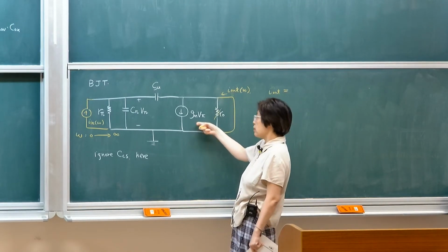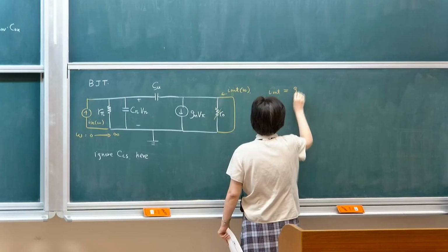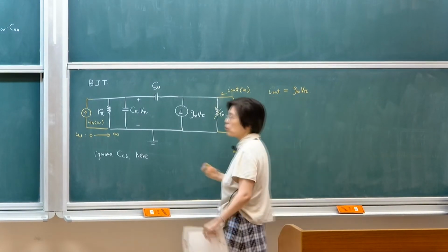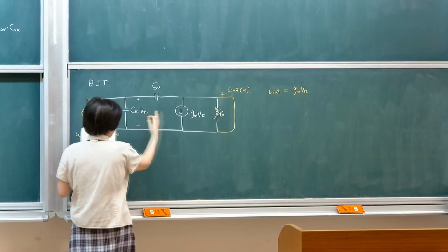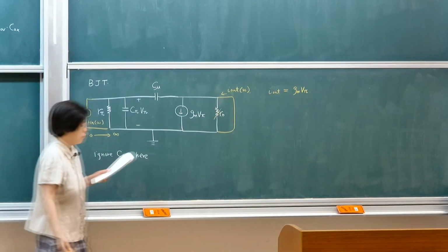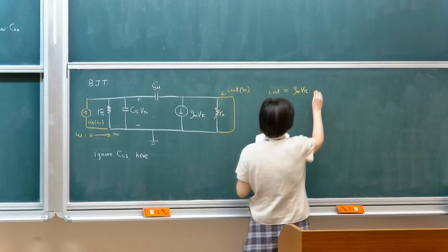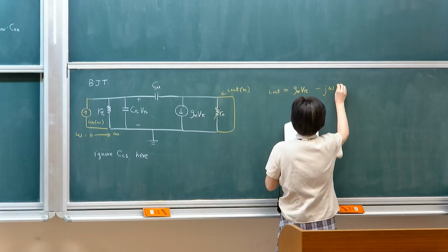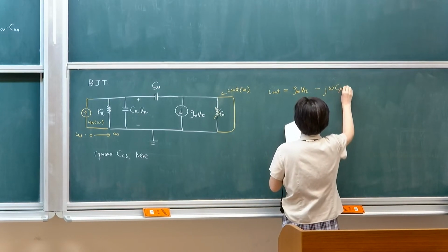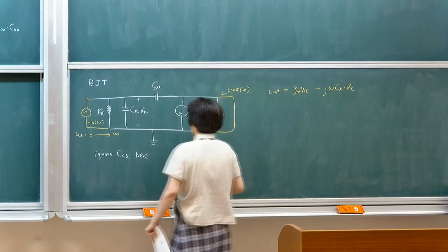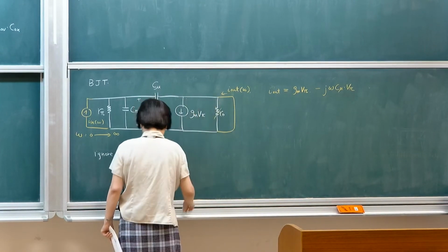One is the transconductance component, which is the effective one that comes from our original low frequency, the main pathway of transduced current to output. And then there is a bridging pathway, which is j omega c mu v pi. So there's current going down. There's two components, 1